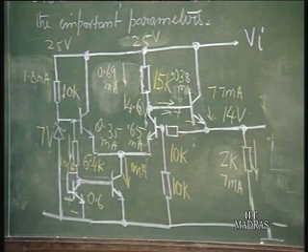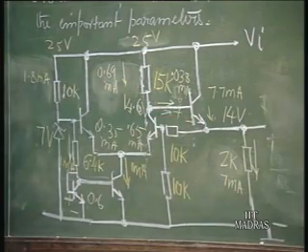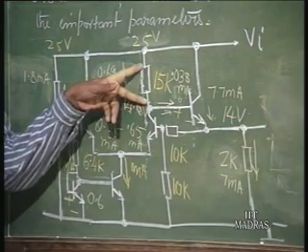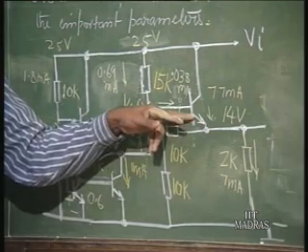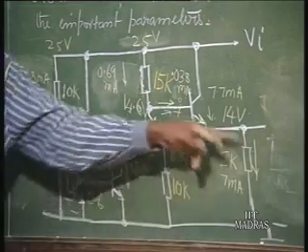That is what we have learnt in our earlier lecture, right. So, the original output impedance is this RE plus 15 K divided by beta. Without any feedback, it is simply RE plus 15 K by beta, apart from the shunting effect of this.